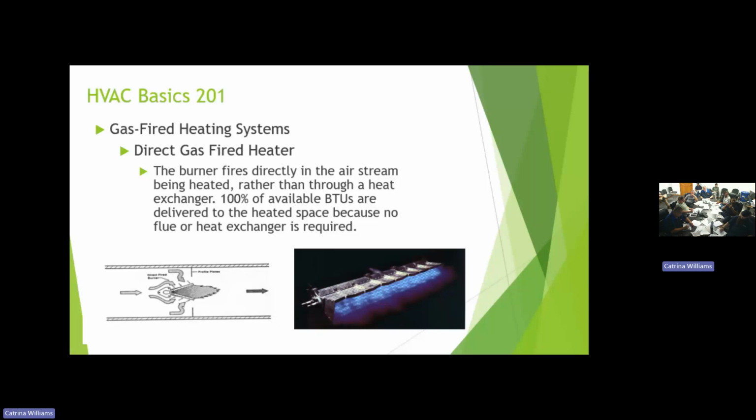We do combustion tests, we fire it up and make sure you've got a good, clean burn. If you get too little air, because the opening is too large, you get what we call the long, lazy flame, yellow because it's still searching for combustion air. If it's a tight flame like this, you're getting the velocity you want.